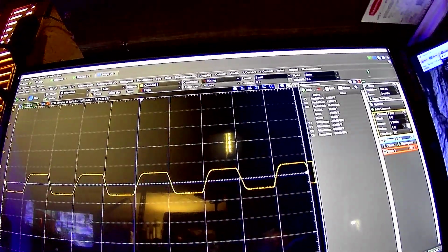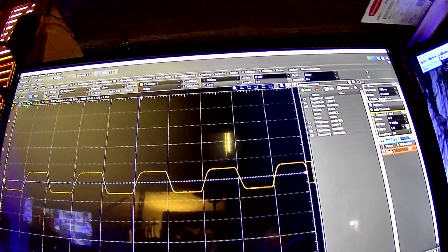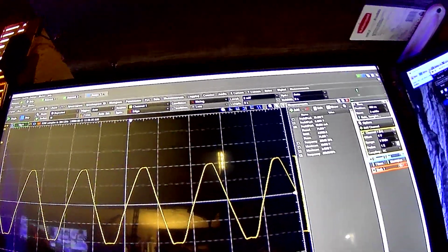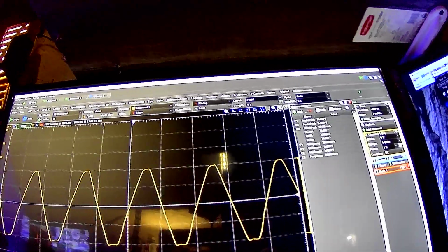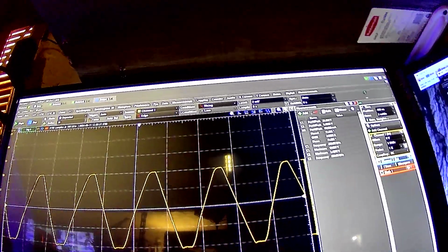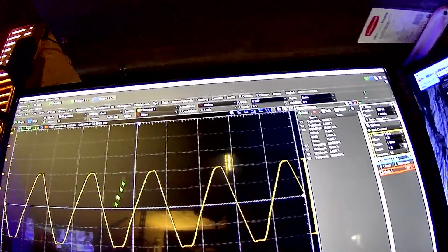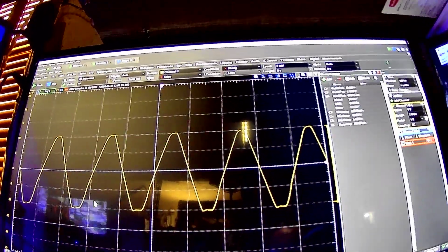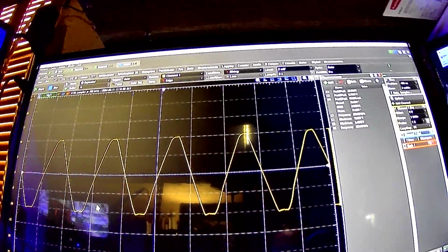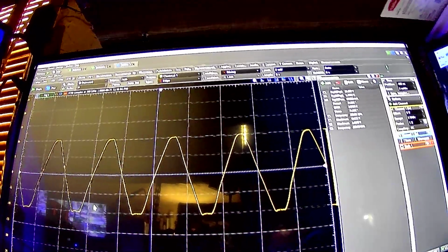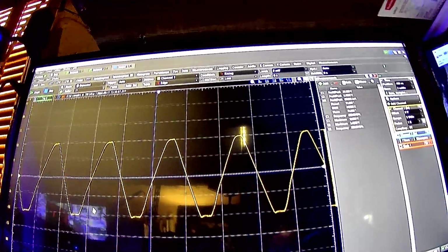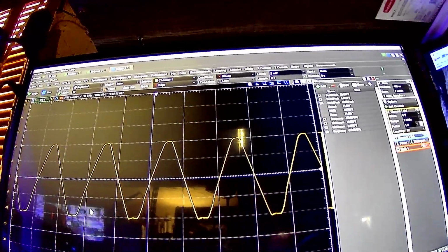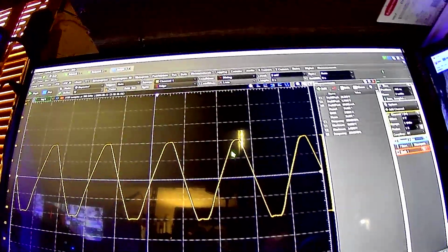But going back to my full power bandwidth, that's what we're looking at. That's the maximum signal you can generate out of this particular DAC, and this is how this amplifier will respond to it. Again, it's quasi sine wave like, and this is 5 times faster, if I'm not mistaken, than a sound card on your computer would generate in its DAC, generating your stereo output. So, of course, it wouldn't go over this.